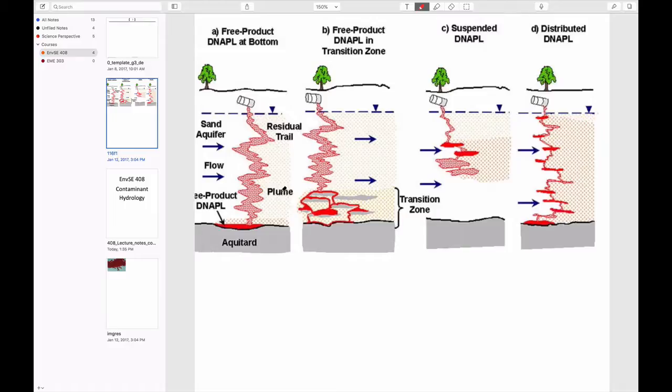And if it does go through the water table, this is a NAPL, then the behavior you'd get would be a chimney, which is a smeared zone. And this would act as a source area for dissolution that gets carried downstream. You see the plume on the right-hand side of this, clean water on the left-hand side, upstream and downstream sides. And it would carry it downstream to some kind of compliance point where you would want to be able to see how large that concentration was.